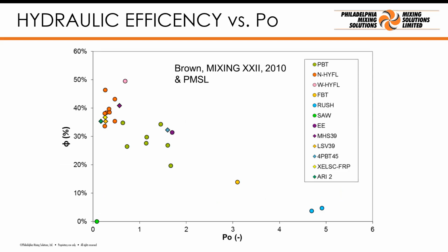So we can measure the flow. We can direct the flow where we want to go depending on the diameter of the blades and also the angle of the blade. So if I have a 90-degree vertical blade, the flow is going to be directed radially out towards the wall of the tank. So now we can define the efficiency, and I actually have an article that was published in 2017,